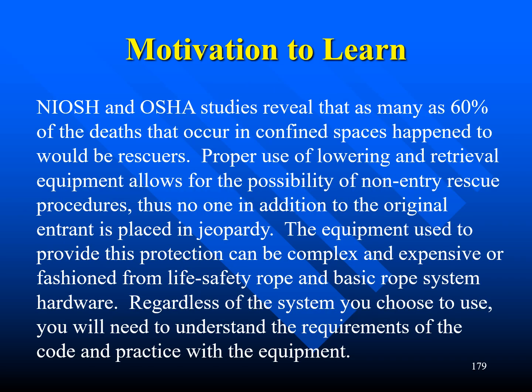This is why it's important. NIOSH and OSHA studies reveal that as many as 60% of the deaths that occur in confined spaces happen to would-be rescuers. Proper use of lowering and retrieval equipment allows for the possibility of non-entry rescue procedures. Thus, no one in addition to the original entrant is placed in jeopardy.